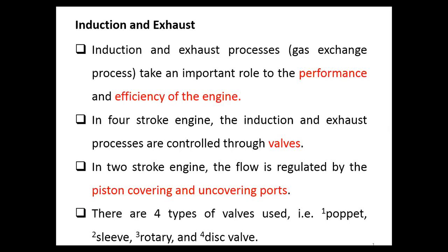Not like in the 4-stroke, where we clearly have one intake stroke and one exhaust stroke, right? I mean, the whole stroke is occupied by intake and another stroke is occupied by the exhaust. But for the 2-stroke engine, we don't have things like this happen. So the scavenging process or the exchange process plays an important role in the 2-stroke engine. Okay, so the induction and exhaust process, or the gas exchange process, has an important role in the performance and efficiency of the engines.